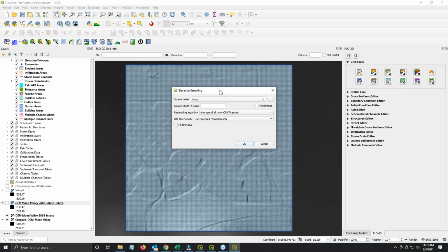If you click this button, what this does is a raster warp. If you take this elevation file right here and apply it to your grid, it's going to warp the original elevation file to your grid, set the grid cell size as the pixel value for the warped raster, and calculate an average from all those pixels that intersect your cell. There are two important things about this that you probably need to know if you are concerned about your elevation mapping. First of all,